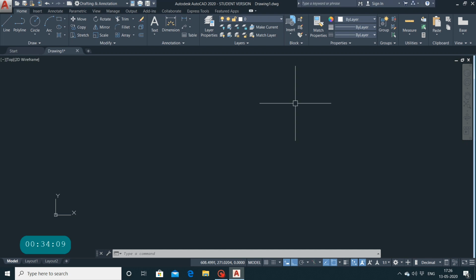For the line there is the shortcut key L. It is used to make simple lines in the drawing. Then there is C. C is used for making a circle. If you type C in the command box, it will make the circle, and C is also typed to close. If we have drawn lines and only 2 points are left, then we can type C to close it.